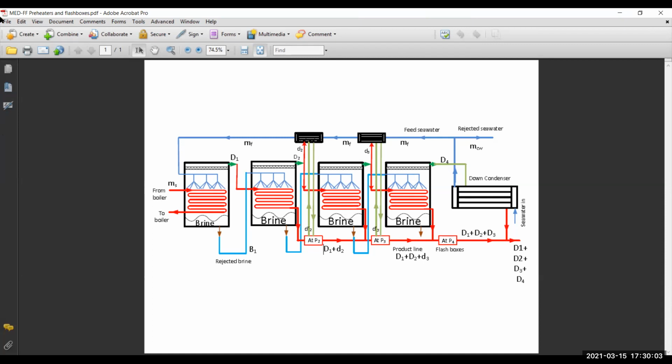And I would suggest that if you are going to analyze a system like this, do something similar to that: draw all the connecting lines between the different components of the system and write the corresponding value of flow rates on top of it. If you got the flow rates correct, then the energy balance is going to be correct as well. Any questions? So we could identify a couple of points where corrections can be done to this figure.